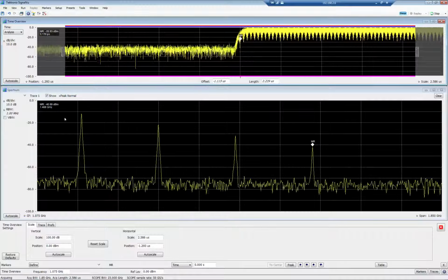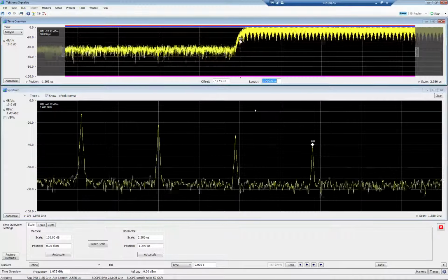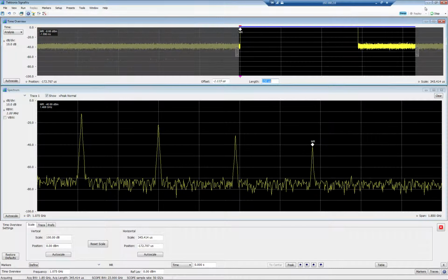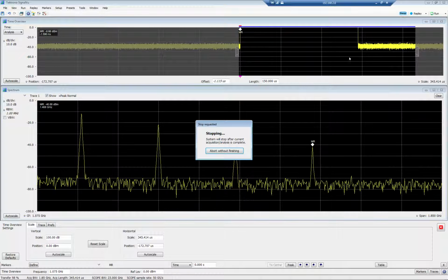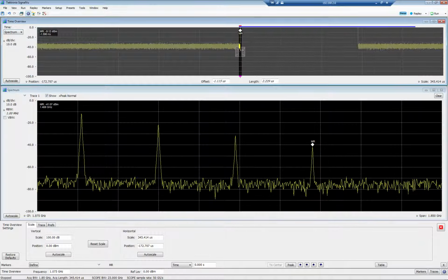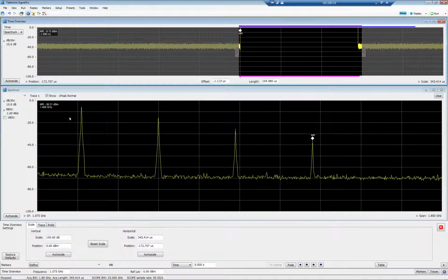So this is how it looks in a spectrum. If we put at this, it should be like 150 microseconds. It's a bit long, so it's transferring, and here you can see the pulse width is roughly 100 microseconds. Now I can go here for spectrum, and I can do a spectrum of the full pulse here, and just press replay. So there you go.